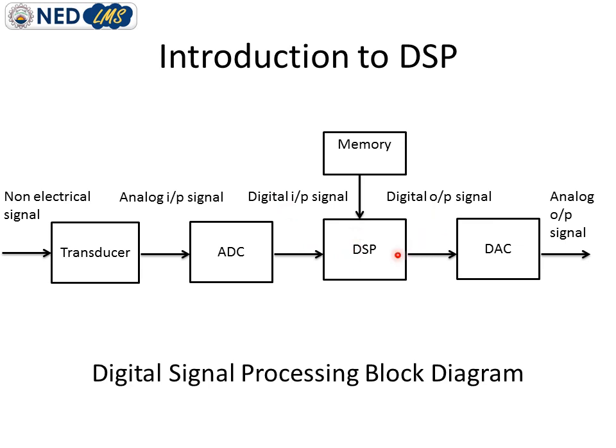So we have two types of signals, or two natures of signals, encountered in this block diagram. The first one is the CTCV signal, and the second one is the DTDV signal. CTCV signals are the analog signals, and DTDV signals are the digital signals. Here we have CTCV signals, that is, it is of analog form converted into digital form, and in the last it will again be converted into analog form, and we have an analog form of output.